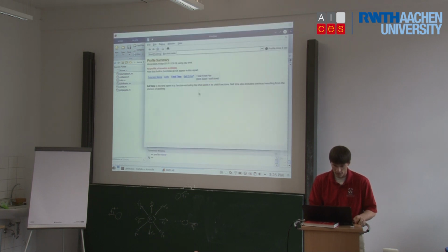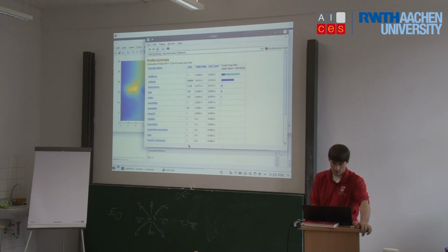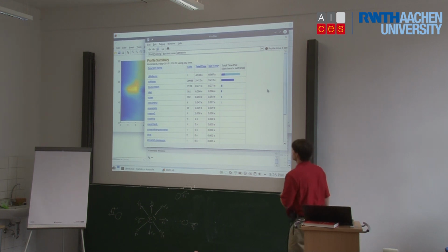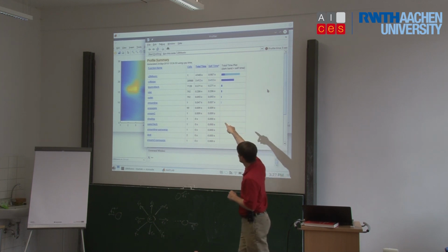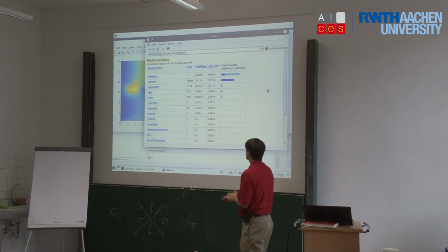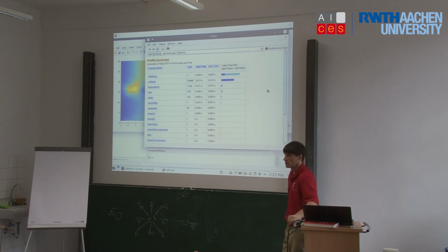Okay. You can turn on the profile viewer, and you can run any code that you want to execute. So let's run LBM basic. Okay. It's going to run this code. It's going to spit out the results. Okay. And then it's going to tell me how much time or its function, okay, and how many times it has called each function. Okay, so in this case, we've called the collision function 20,988 times. And we've solved this problem on a very small mesh, and we've only iterated 100 times. So we're not anywhere close to really converging this problem.